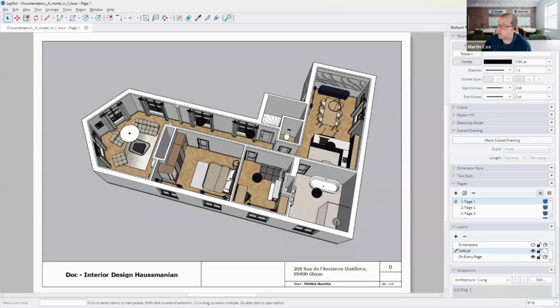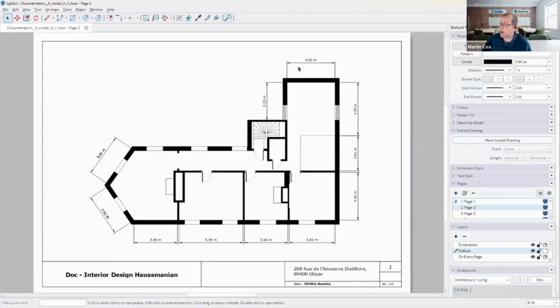And we can import the scene views within layout. So we have a number of pages, and this has been preset. You need to add these drawings, but these are actually links to our 3D model. So if I make changes within our 3D model, they will be changes within our views. We have those different views that we've spoken about. So we have our view here, and this one's been dimensioned. If I select my dimensions, I can say, actually, I'd like internal dimensions within that wall as well. If I just double click, it will place another dimension for me, similar to the push-pull there as well.